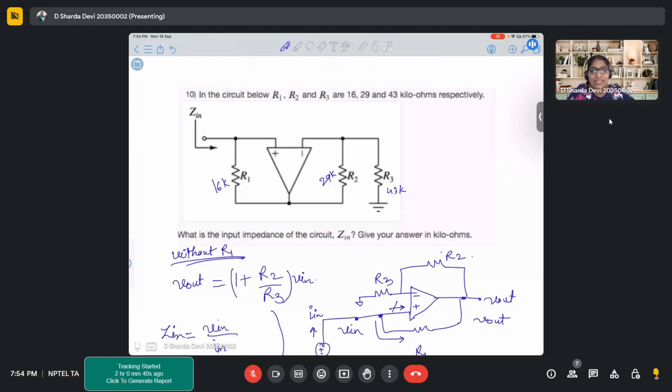When do you need that polarity? When you are calculating, let's say, gain, and you know that for a CS amplifier you should get a 180 degrees phase. Now that 180 degrees phase, how do you represent that? You use a negative sign. Formulas like GM or current will ideally be positive only. Then positive or negative is majorly used to show the phase shift.